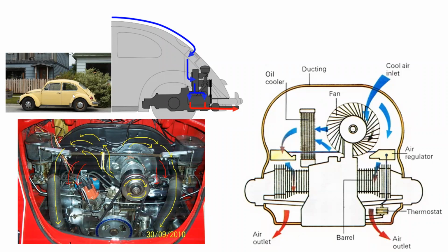That's one of the reasons for these vehicles to be so popular: less maintenance, fewer components to worry about. Anyways, the airflow comes over the top of the roof, then goes through these holes at the back, and that airflow goes into a baffle around here. This is the section where the baffle is. Airflow comes through these holes and goes into the baffles itself. This section is where the cooling is happening.